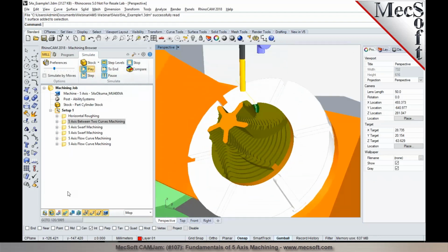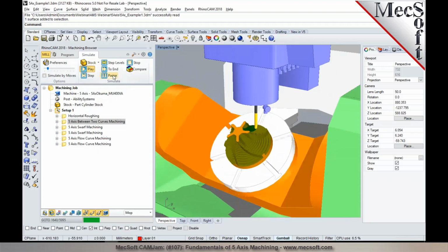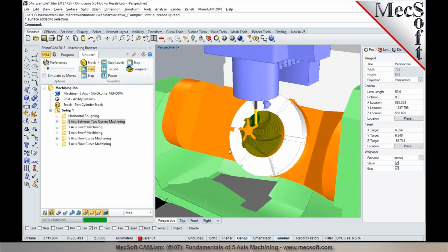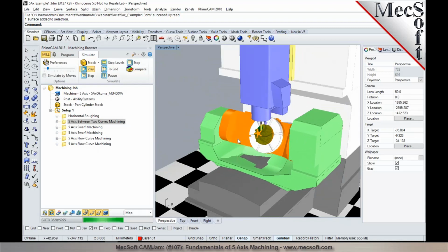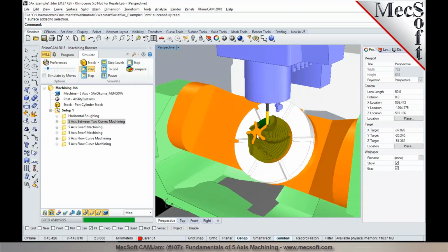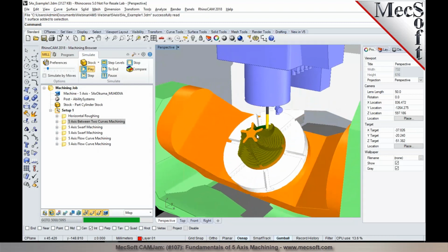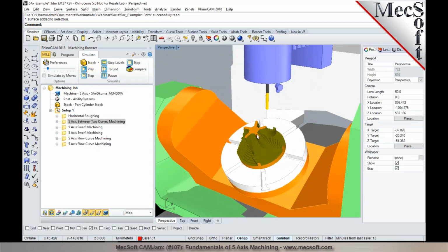And I'm going to run a verification for this. And with the machine tool being displayed, machine tool simulation selected here, you'll be able to see the linear and the rotational axis motions. So you could be programming a combination of different 5-axis toolpath methods, and you could do a combination of both indexed and simultaneous methods as you're programming the part.